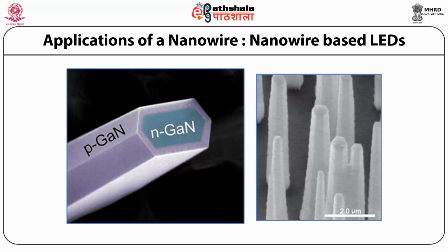Gallium nitride emits light when holes and electrons recombine at a junction created by doping the crystal to create p-type and n-type regions. These layers are formed by a variety of deposition methods, typically on a sapphire or silicon carbide substrate. Conventional methods produce crystal with relatively high defect densities.